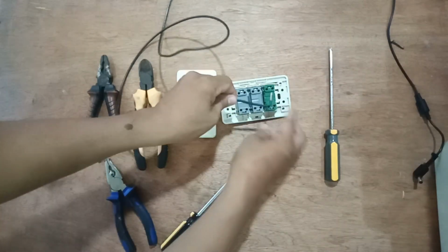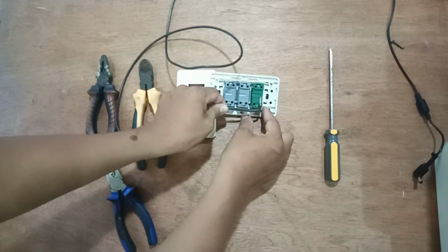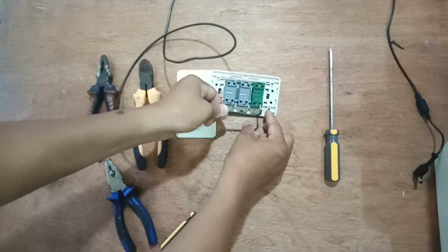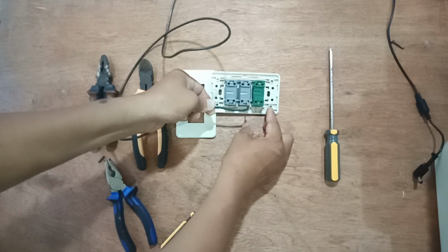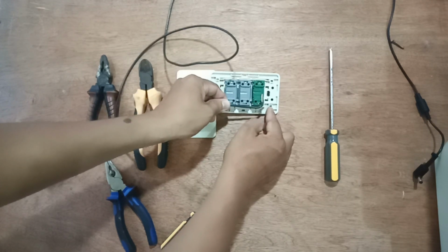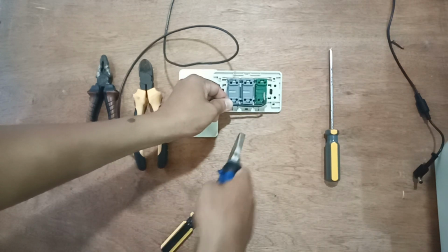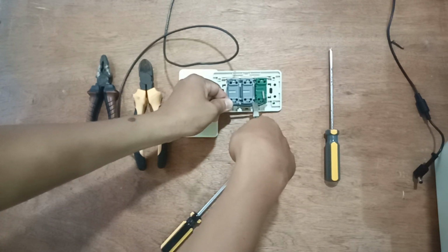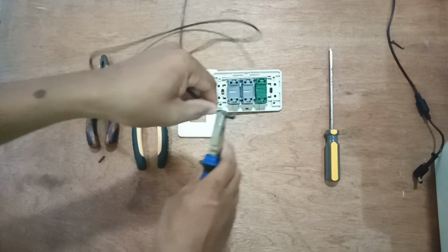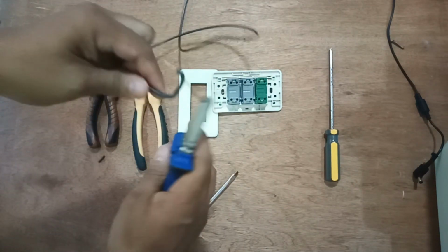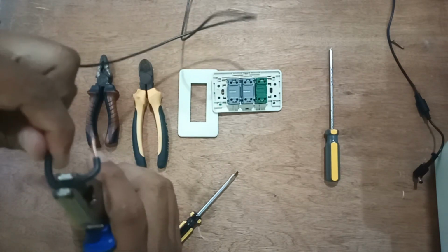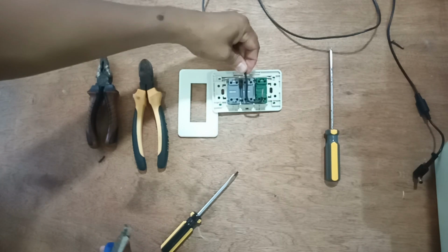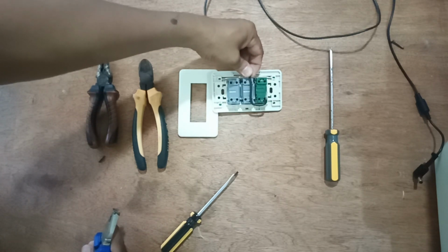Let's say we will start on the other side in this position. We are going to jumper from this portion going to the other terminal of the single pole switch. So we have to do this this way, and then bend right here also. As we bend the wire like that, we can now estimate if it is really exact for the location.